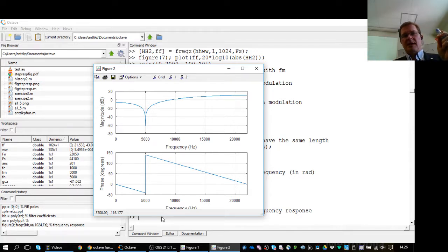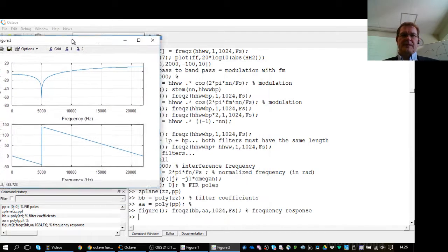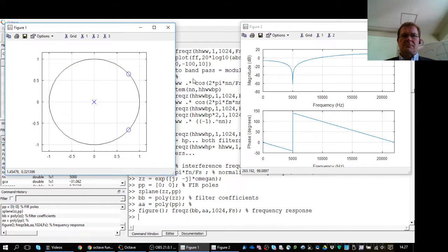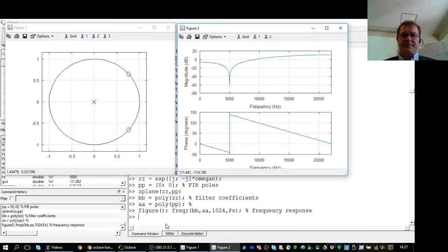How accurately at 5 kilohertz do you actually have always that notch, or is it moving a little bit? The narrower you make your filter, the less tolerance it has against small changes in the frequency. And sometimes you may need to make an adaptive filter to do the filtering, meaning a filter that measures the frequency and then tunes the notch accordingly. But well, this still, that's a good start.